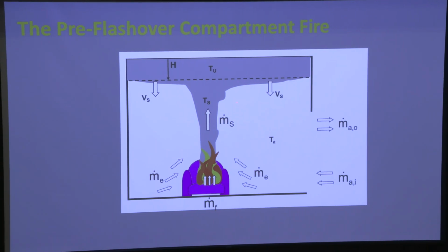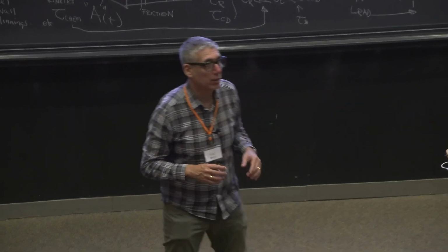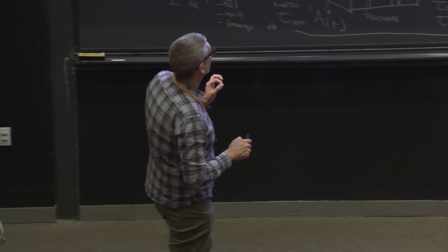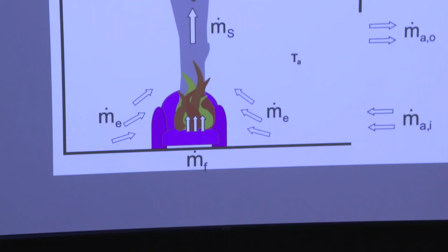Now, obviously, the fluid mechanics eventually have to encompass the entire compartment, because the entire compartment is going to create a flow. So the flow is going to come in through the boundary, enter the compartment, combust in here, go up, and then come down and then go out. This is basically an ambient pressure system where effectively pressure is fully translated into fluid mechanics, so it behaves as compressible flow. Okay, it's only incompressible in the buoyant term. In other words, the Boussinesq approximation applies,